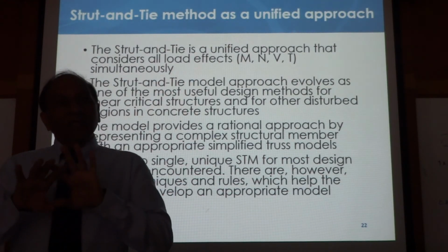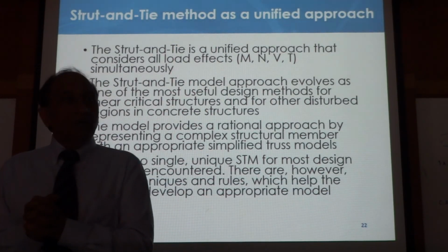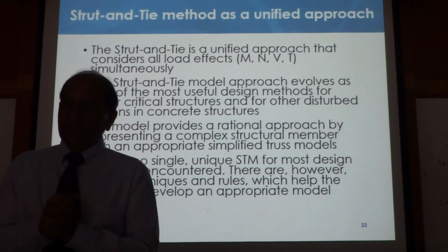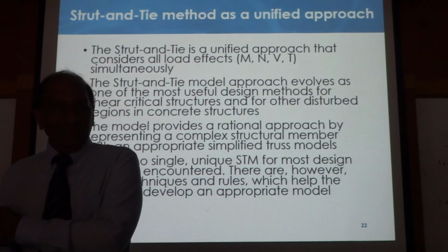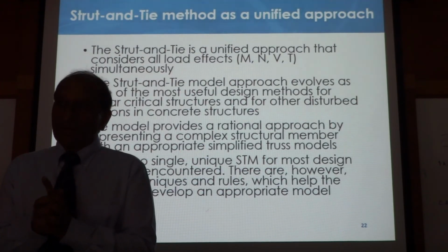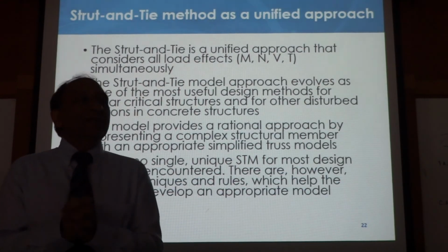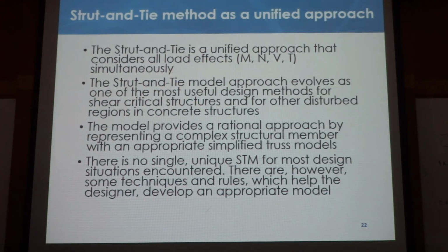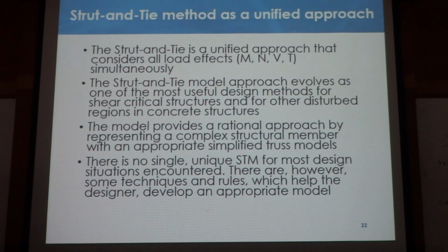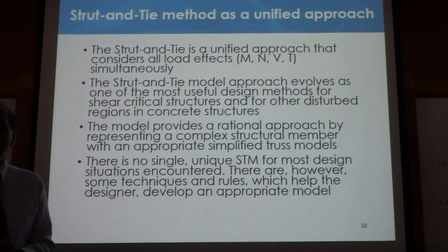And we say, okay, the entire capacity of a concrete member in a certain situation comes from tension and compression, tension taken by steel, compression taken by concrete. End of story, right? If we make that assumption, then we come to the idea of the strut and tie model, in which we can resist all forces. This is a very useful and rational approach, and this is a lower bound approach.